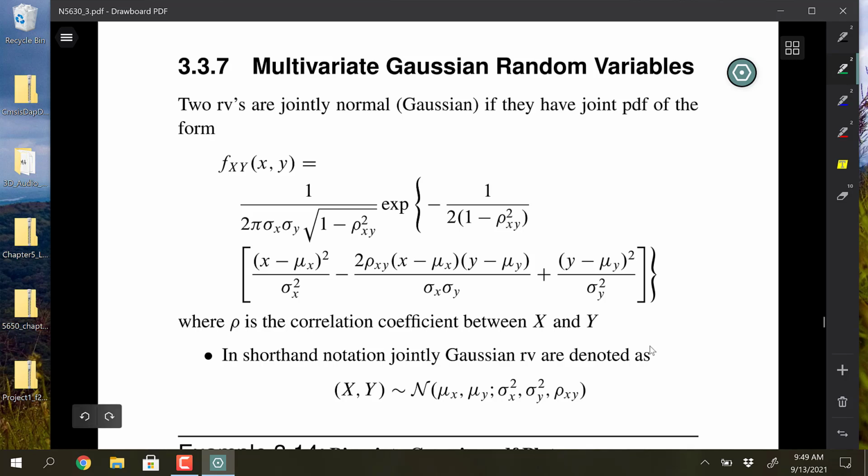Multivariate Gaussian random variable, this shows up fairly often in modeling, where you've got correlation between random variables, namely samples or in phase and quadrature. What will introduce correlation in digital communications will be filtering or memory of some sort. So in a channel model, you won't be able to say that the two multipaths are independent of one another as a result of correlation between the samples, right? There's a memory relationship, so you can't just say they're independent.